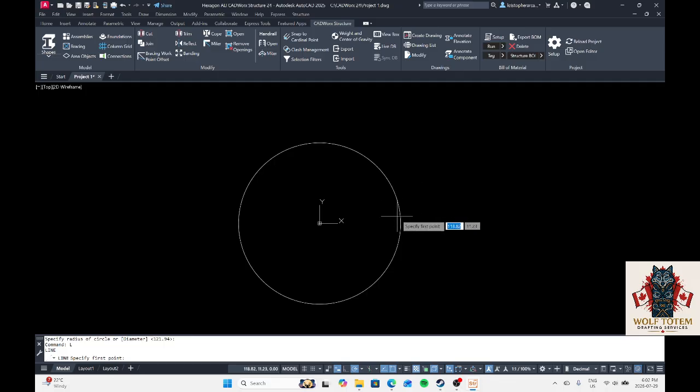We're going to draw a line, and we're going to go to the center here to draw out. Hit escape. If we want to repeat a command, all we have to do is hit our spacebar and it'll give us back our line command instead of typing L again. And we're back to where we pretty much started with this.